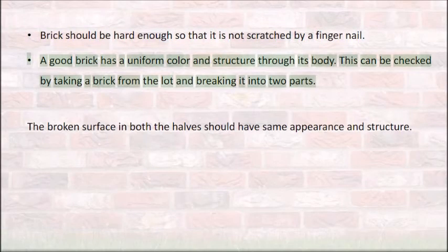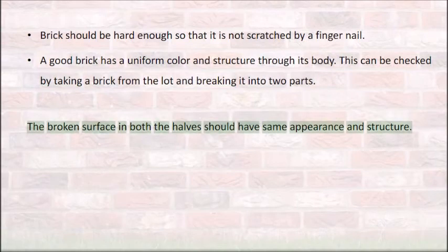A good brick has uniform color and structure through its body. This can be checked by taking a brick from the lot and breaking it into two parts. The broken surface in both the halves should have the same appearance and structure.